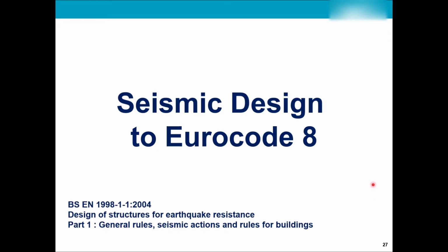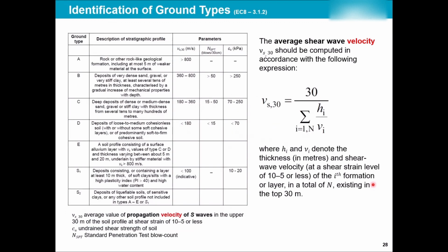But now let's very quickly review what the seismic design based on Eurocode 8 is, following the same concepts and philosophies that we discussed: dissipation of energy, ductility, capacity design, and see how Eurocode integrates these. If you remember, the initial step of Eurocode was to get a response spectrum, the same response spectrum where you apply an earthquake to different buildings with different periods, and you see how they behave, so you get the spectral response spectrum or spectral acceleration of them.